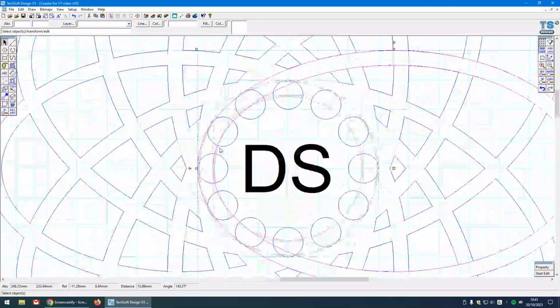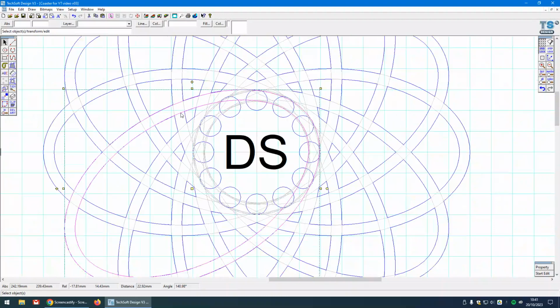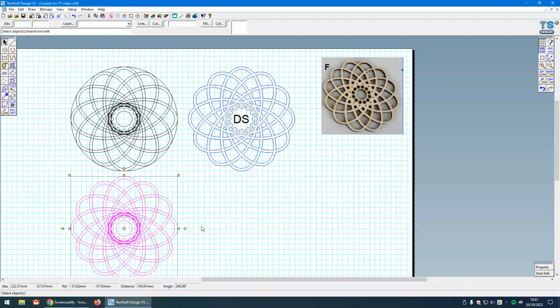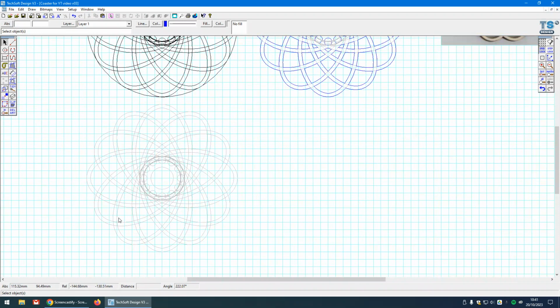On this design here, you can see that as I was clicking gray template entities, it's only getting one at a time. Now I can select them all in one go. So I should have done that with my previous video. That was my mistake. I'm going to show you a fast way now of adding in all these contours.